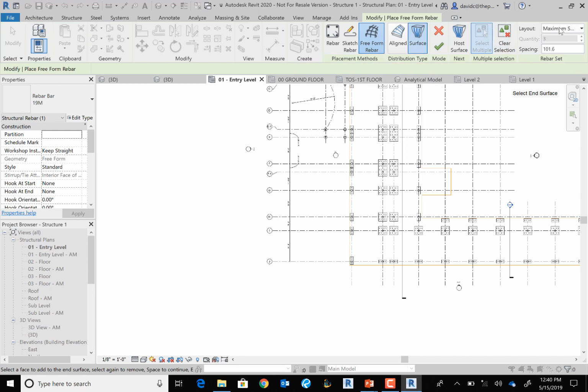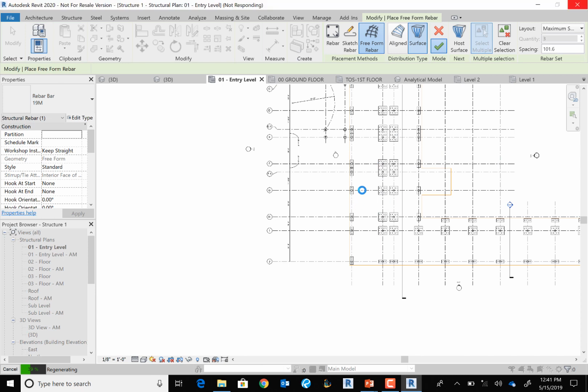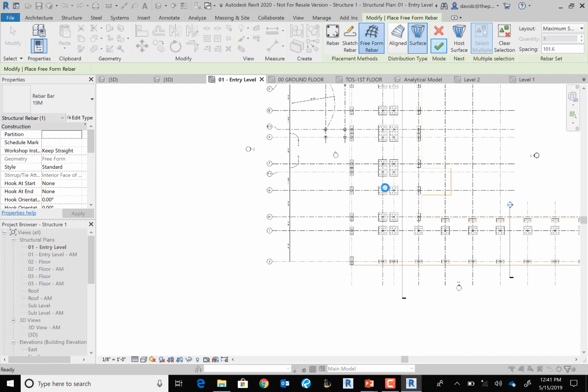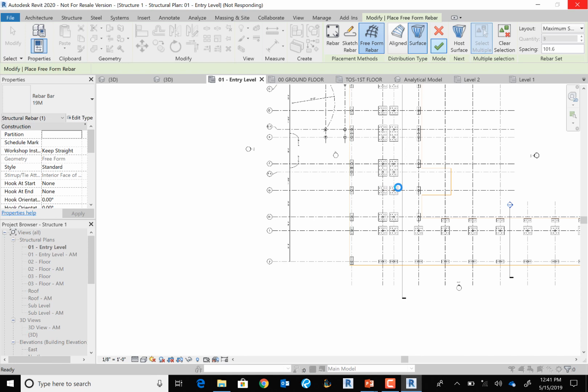And you're going to see it's going to go ahead and tell you pretty much exactly how many bar that you're going to get, but going to gray out here. It'll tell me that number after it's gone ahead and placed them in this floor. It's very nice. It follows curves. Like I said, it will actually just warp these around. If you have shafts, it'll cut the rebar for the shafts, everything like that. Surface is moving a bit slow after that other connections that we did.